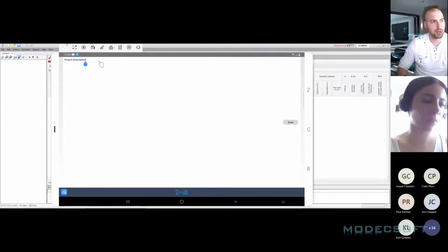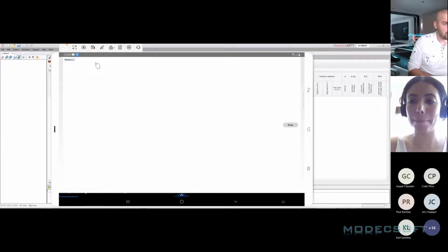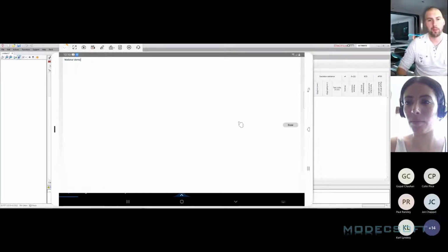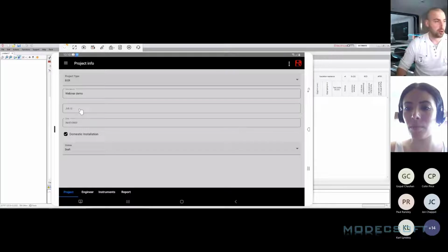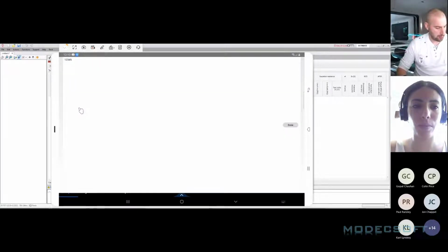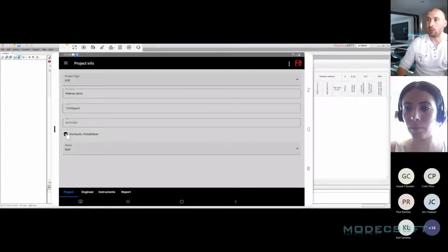We can give this project description information then. So here I'm just going to call this webinar demo. And we can give it a unique job ID. These things will match into the software. So 2, 3, 4, 5. And I'm going to leave it as a draft, and we can make it either a domestic or a commercial style. What this will do, particularly with EICRs, it will slightly change what information is within the inspection schedules later on when we're doing our inspection schedules and linking them to issues within the mobile app.